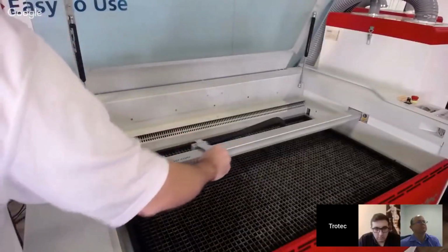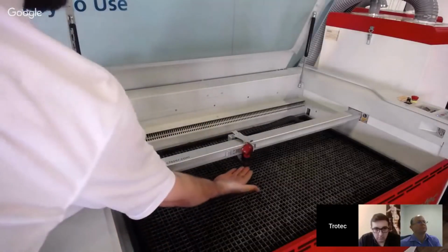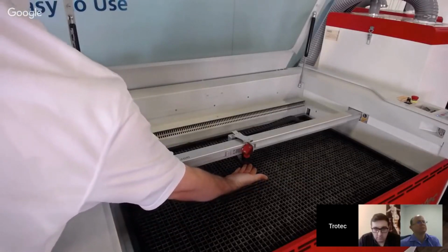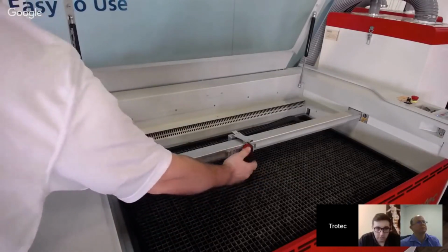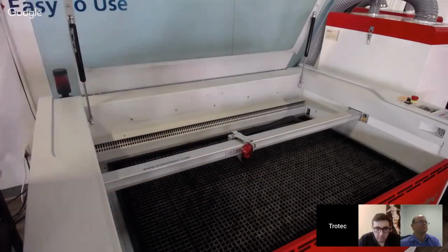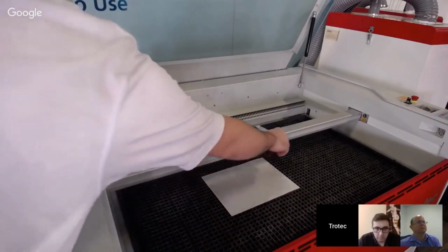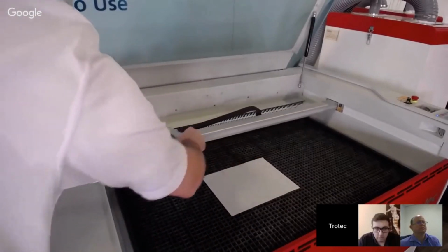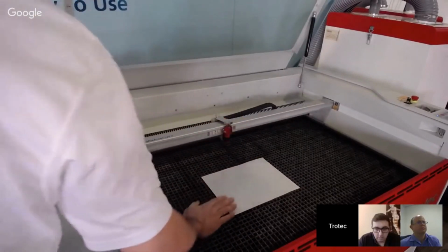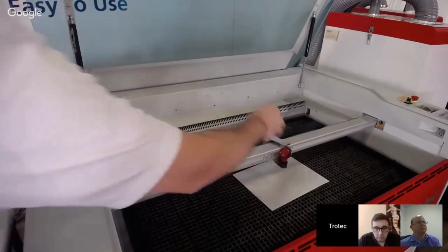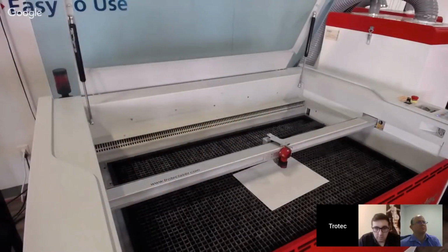So if I move this laser head, you can see our red dot pointer there. That is where our crosshairs are going to be. So if you did have a piece of material, maybe you're cutting out a slice of paper here, and you didn't know where you wanted to place it, you can then move this anywhere you want. Place your material, or place your laser head over the material. And now there's no thinking about it, really. You just go back to job control.